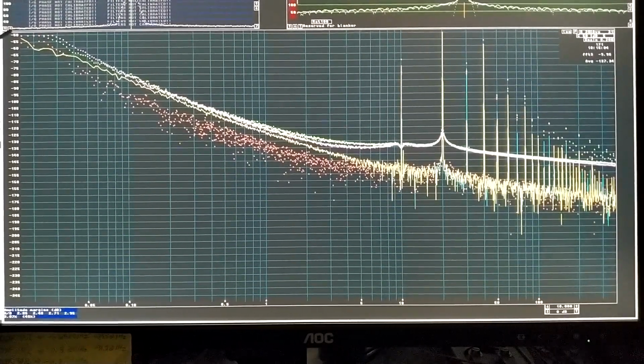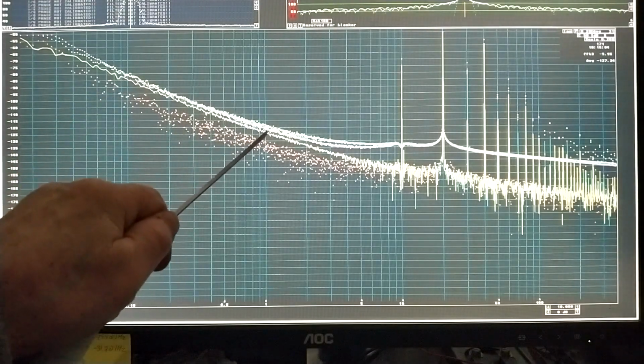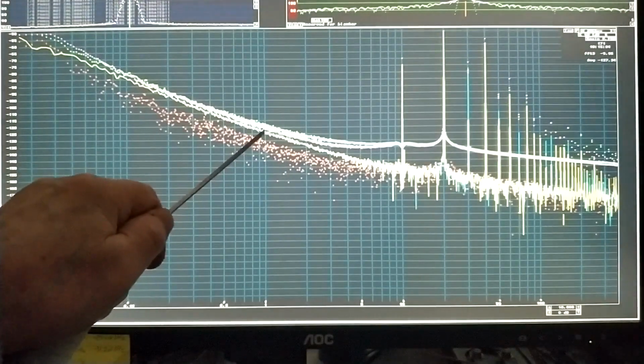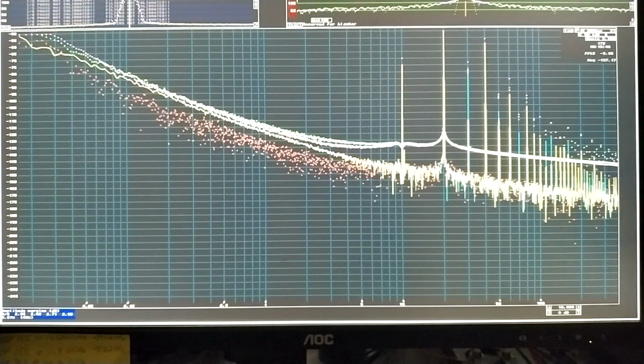Here at 0.02 hertz, the yellow trace is far below the green and red, and the imaginary part is stronger than the real part. Usually I see the opposite, that the noise goes up when I go very close to the carrier. The level at 0.1 hertz seems to be minus 85 dB, and at 1 hertz it looks like minus 124, and this is significantly better, although it's not the best I have seen with this unit.